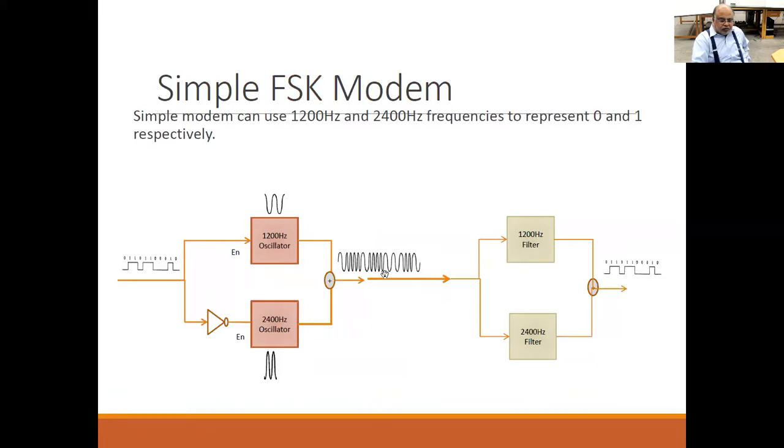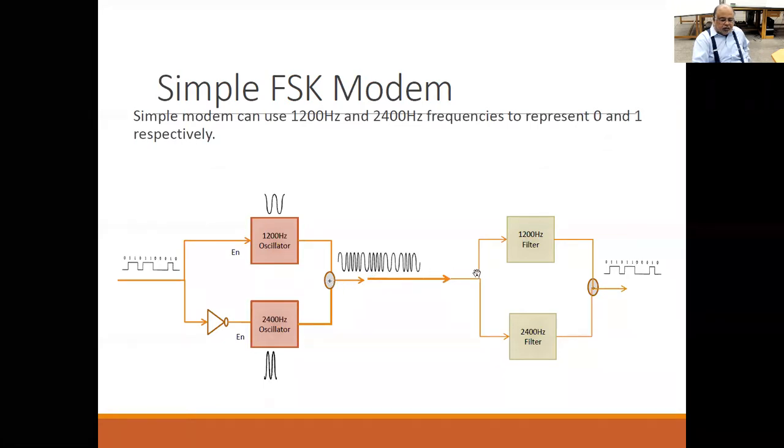The same was the case at higher frequency levels: you could embed a carrier frequency so the receiver end would have exactly the same frequency clock, a sinusoidal waveform. Because of PLL, you could have a continuous synchronous sinusoidal waveform over here, totally in phase with the one transmitted, because PLL would ensure that both oscillators on the receiving and transmitting ends had exactly the same frequency.